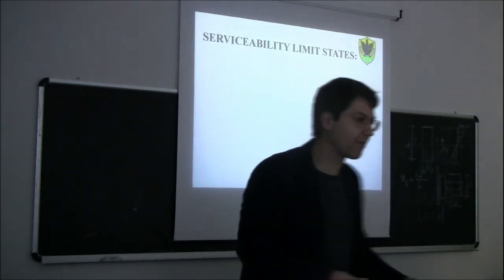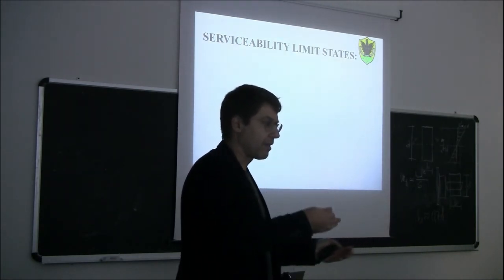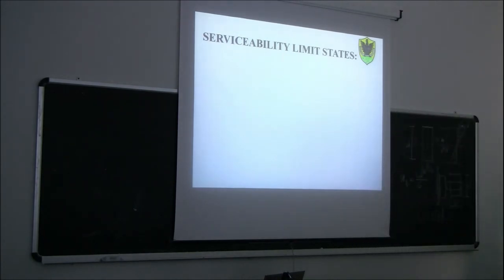Well, particularly when you have very long beams, usually the serviceability state is quite complex. It's usually maybe the governing design equation, the serviceability state, and the second one that will be critical is lateral torsional buckling, as you will see at the end of this presentation.